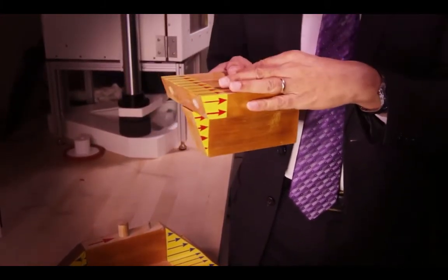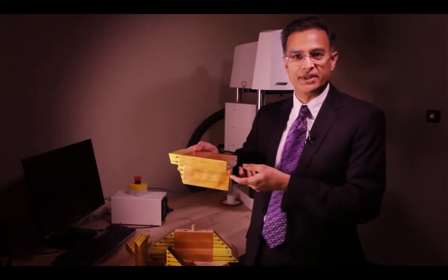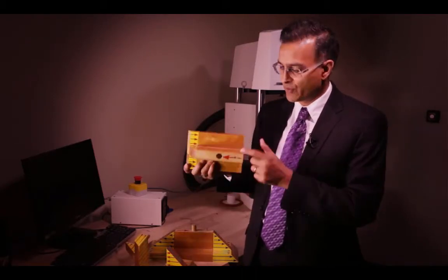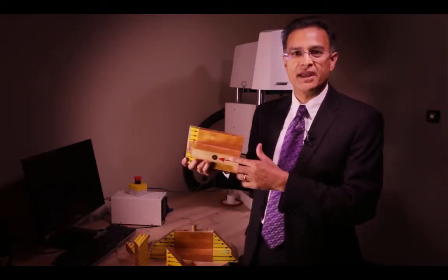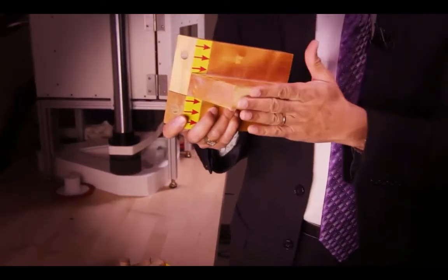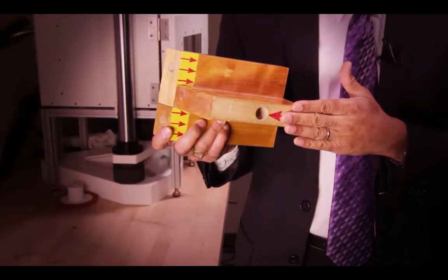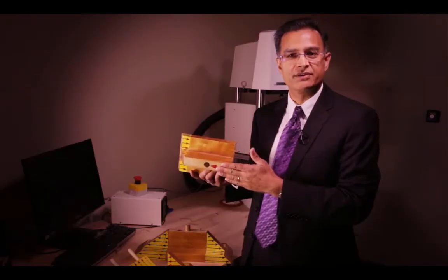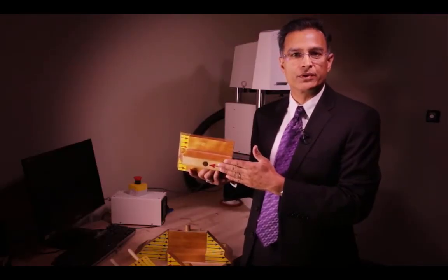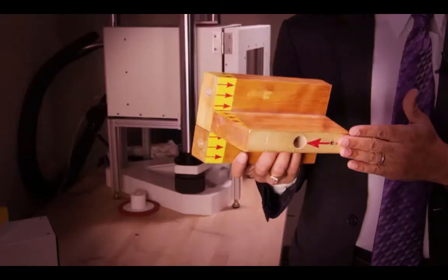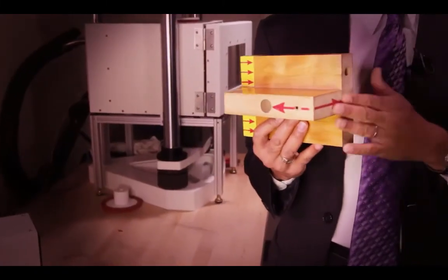And to keep the system in horizontal equilibrium, so equilibrium in the x direction, our usual coordinate system, I'm going to need a force here to resist that. And if there's a force on this surface here, I can divide by this area here, and I'll have the shear stress on this surface here. Now, if I have the stresses on this surface, I can use our understanding about moment equilibrium in terms of stresses. That tells me what the stress on the orthogonal surface is. They have to be equal to each other. So now I have a stress on this surface here.